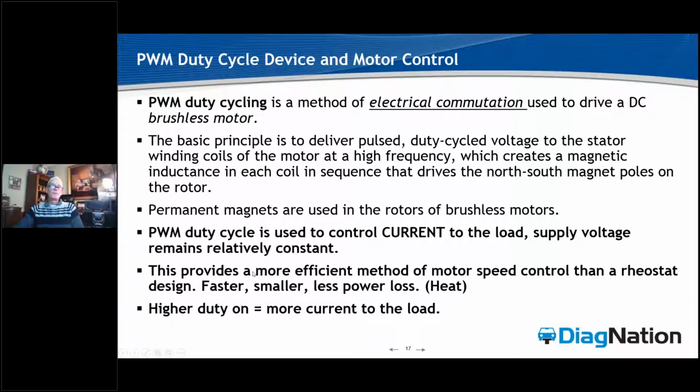Okay, now in the case of PWM, the voltage stays relatively constant. If you ramp it from the lowest current, a fuel pump, let's say, the slowest speed or lowest current, to the highest speed or highest current, the difference in voltage, guys, is sometimes less than 1/10 of a volt. I've seen it at 2 or 3/10 of a volt difference, meaning as you increase the current, necessarily the amplitude of the signal will increase, but it will only increase to the engineered limit of current control in that circuit.